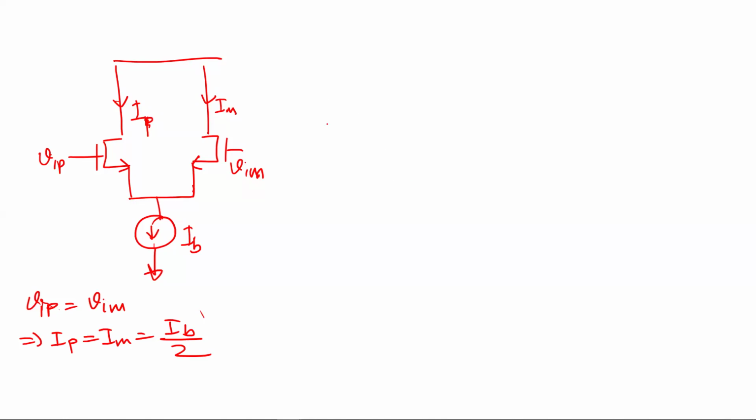So whatever transistor you have here, this is W over L. This is also W over L. So why does the current split between these two? So I assume both of them are in saturation. Yeah, go ahead. Yeah, symmetrical. Obviously from symmetry you say, yeah, it maybe splits. But then from the current equations, how do you prove it? So an assumption is they're in saturation. In linear it'll also be true, but let's say it's saturation.